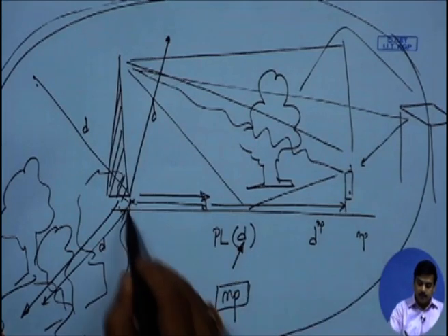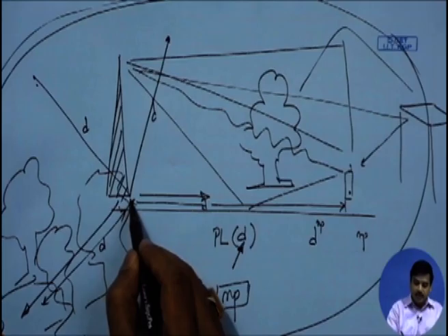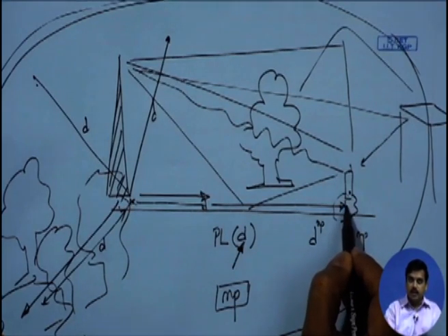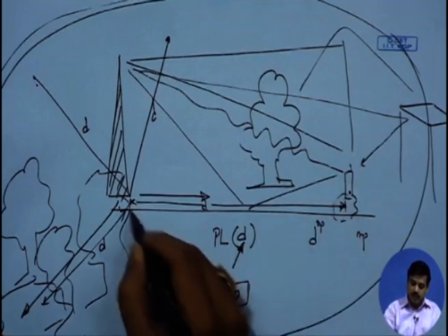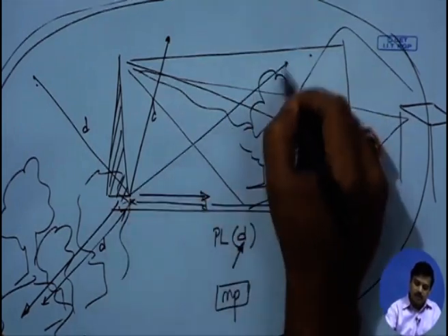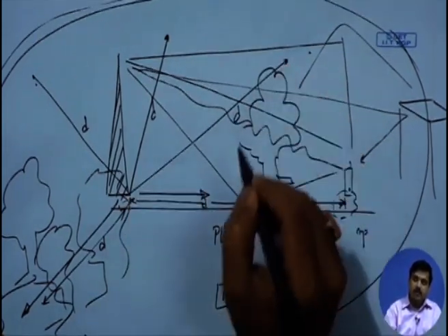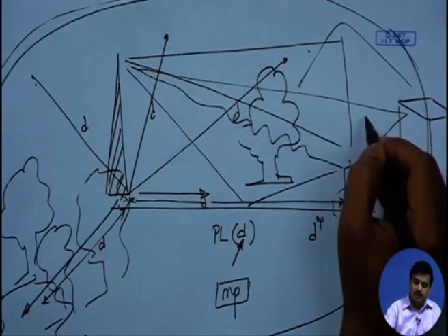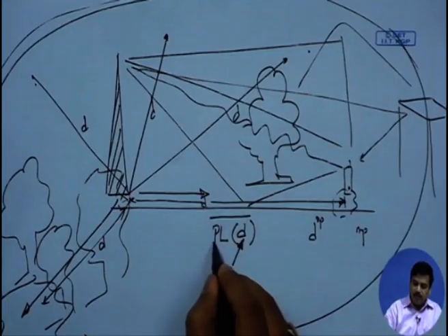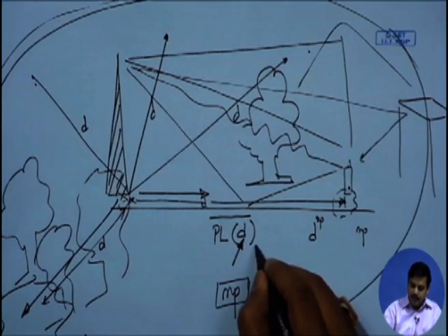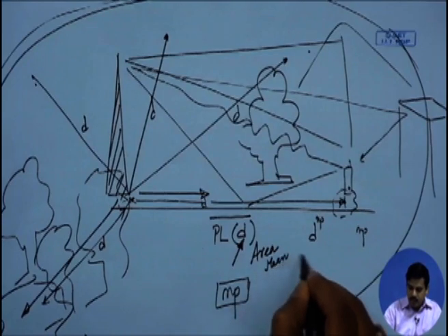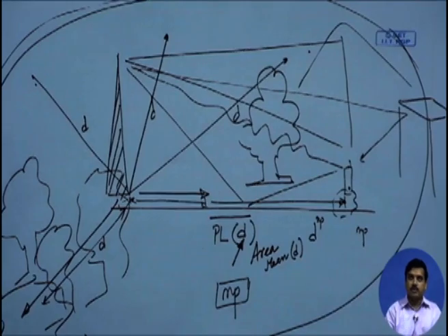So, what is typically done for path loss parameterization is that we would go to a certain distance d, do a lot of readings over here, take the values and store the average. Then we would go to another direction at distance d, and do a similar thing across the whole area in different directions. What we get is the average path loss as a function of d, and it is also known as the area mean, as a function of separation distance d.